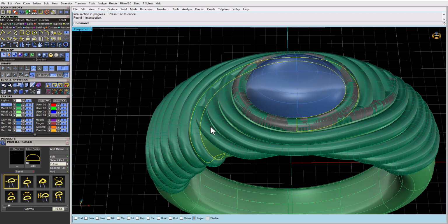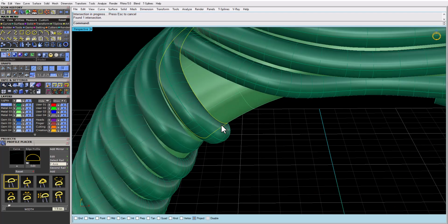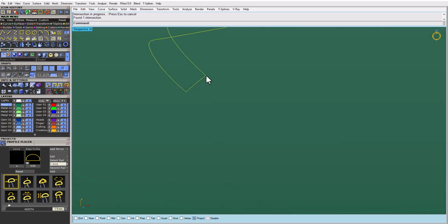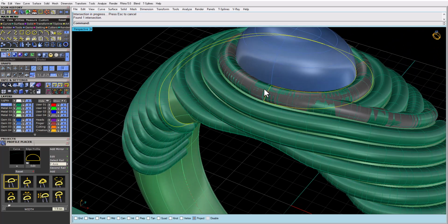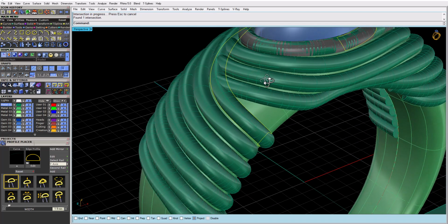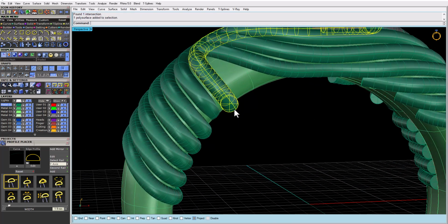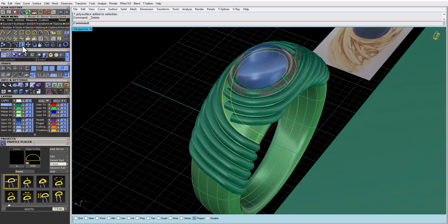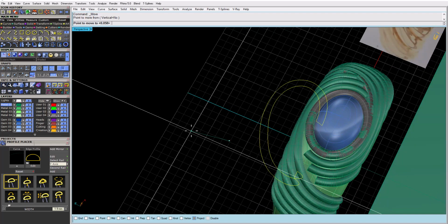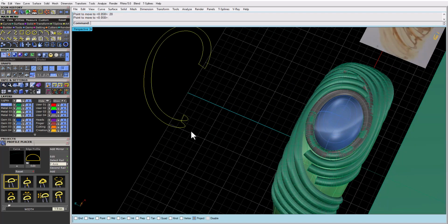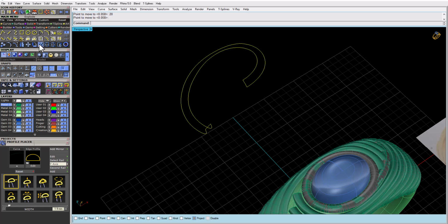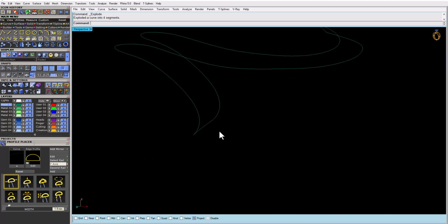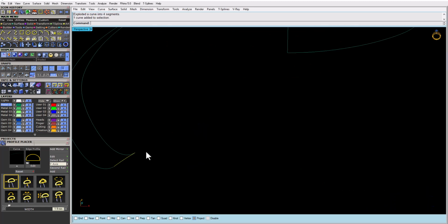So there you have it. You have your two cross sections. You can add your profile at the end over here and one over here. Okay, and you do a sweep 2, right? Okay, let me just show you one example. So this is what I would do. I would just take this away from the main design, explode it, and